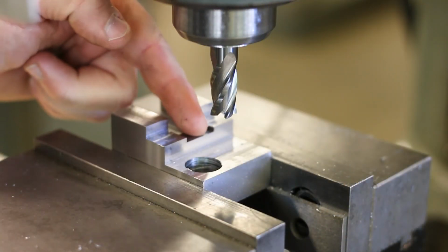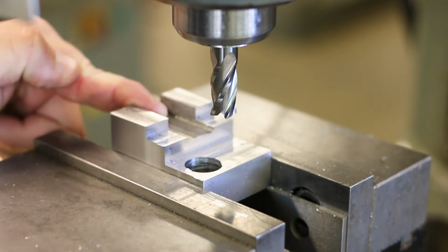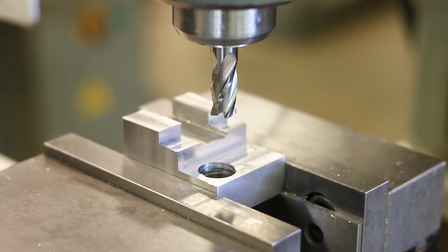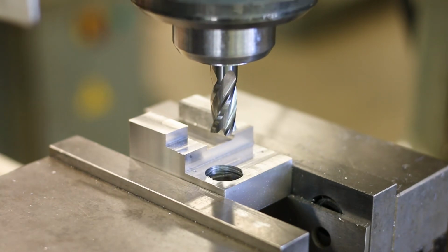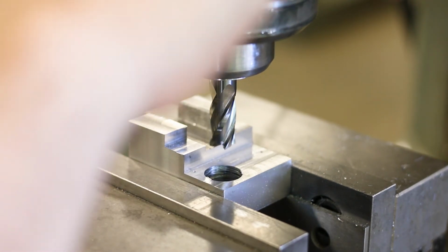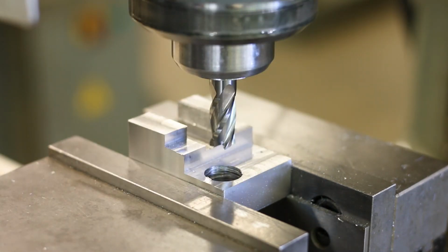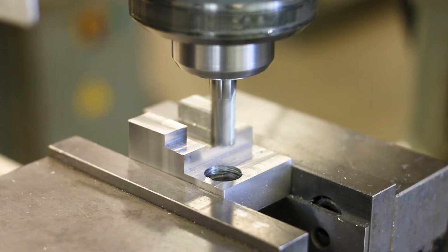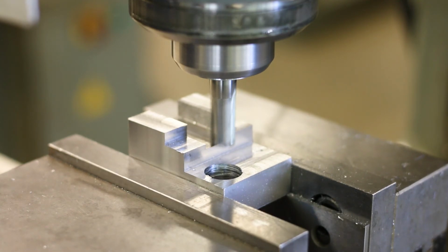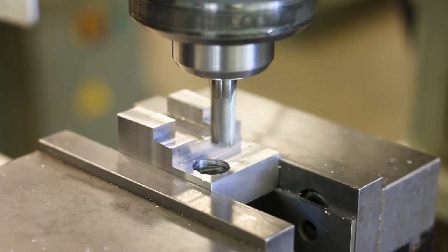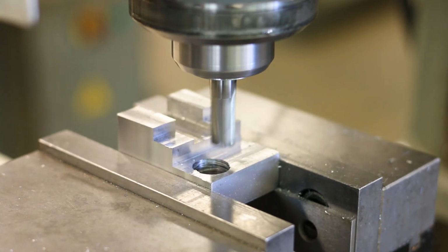Okay, so the first thing we're going to do is get the depth of the slot down. So I'm just going to go ahead and come over here over top of the slot, come down pretty close with the quill, lock it down, turn on the spindle. Okay, and then I'm going to touch off with the knee right there. Okay, call that my 0. I'm going to take a 5/1000 cut right through the center, and I'm going to set the power feed for this.